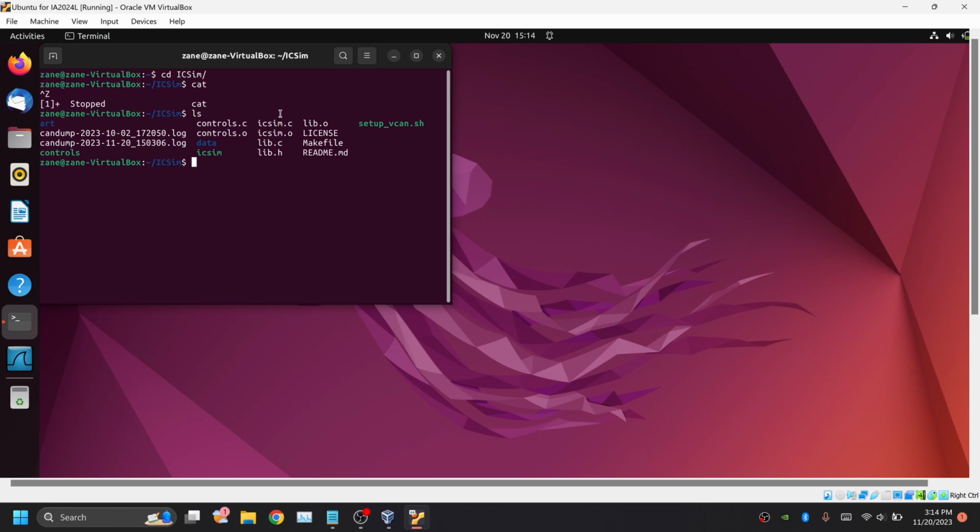But before we can load up those two programs that we need, we have to run a few commands here. First of which is sudo modprobe vcan. We'll go ahead and type in our password here. You'll notice that these commands don't really give a confirmation that they've worked aside from just starting a new line. So just keep that in mind, but they are working.